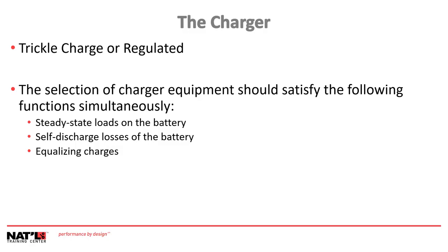In the sizing of charger equipment, the steady state loads, equalizing charge current, and self-discharge current should be added to arrive at the capacity of the charger. Select a charger with ratings that exceed or equal to the sum of the currents required.